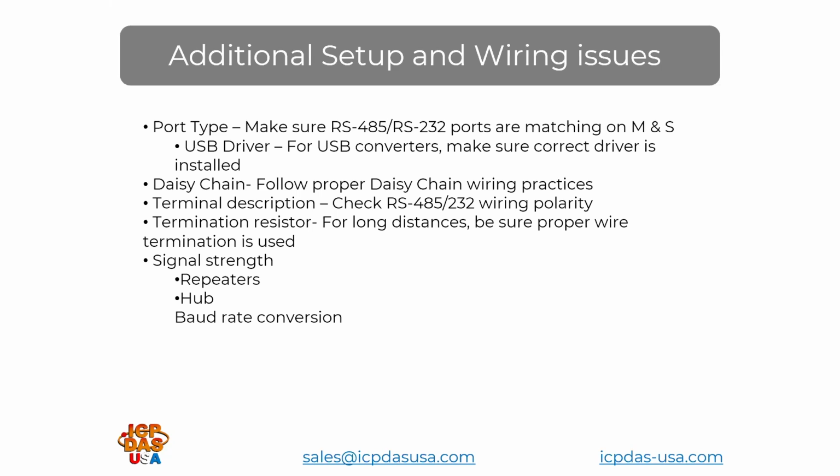When you plug some of those into the PC, Windows will sometimes pick the default driver, which is usually a Prolific driver that may work partially but may not work completely. So I have seen that many a time. For daisy chain wiring, be careful. It can be a little tricky to debug.